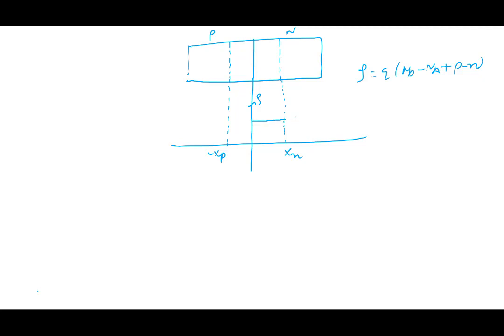Rho equal to q Nd. And in this region, there's an approximation that's being done here. What did we say in this region? Electron density is very small. Hole density is very small. There is no Na. So what is rho equal to? q Nd. So we make an approximation that rho is equal to q Nd right up to this particular point and falls to 0 here. It's not going to be exactly like this, but there's nothing that changes abruptly. We can come back to that. And rho is minus q Na and goes like this here.